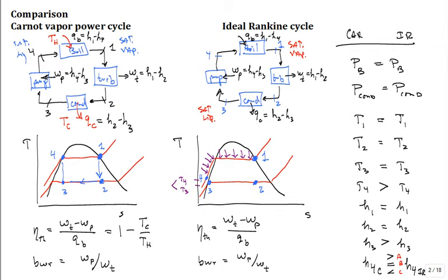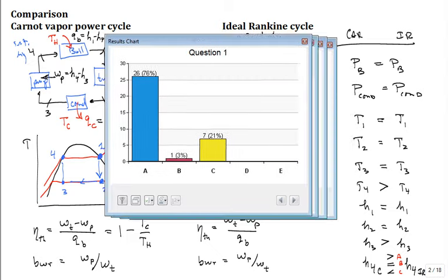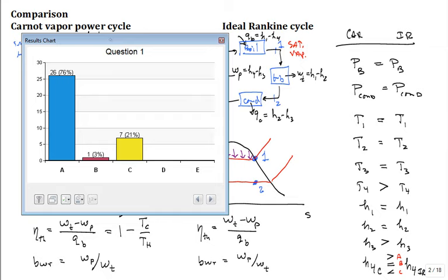All right, let's see where we're at for the results. Okay, well, we're not 100%, but the enthalpy is a measure of the energy content for the fluid. The definition of enthalpy, H, is U plus PV, true? And so you could think of it being high because of high temperature, and I know pressure and temperature both affect you, but also because of this high flow work term, this high PV term.